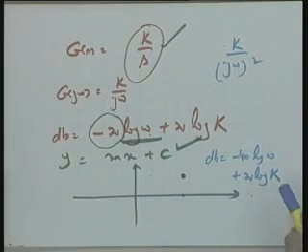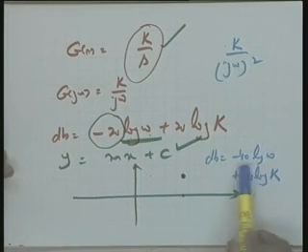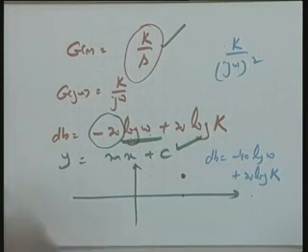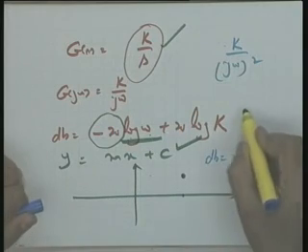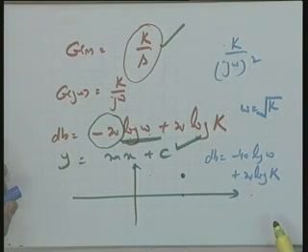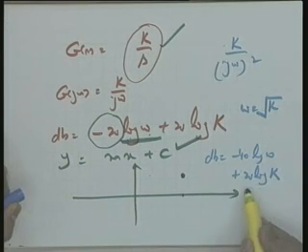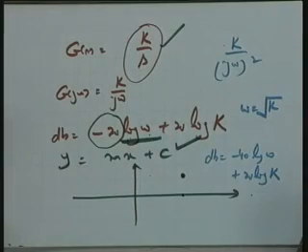Yes, please see that this is the point, it needs your attention. If you identically increase it, you see your equation is now dB equal to minus 40 log omega plus 20 log k. So either you take omega equal to k, there is no problem. No, the same thing will be applicable there as well: omega equal to root k. If you take that, you can pass it through this particular point, or if you take omega equal to 1 rather, then it will remain the same, because 20 log k is the point through which the line of minus 40 dBs per decade will pass.